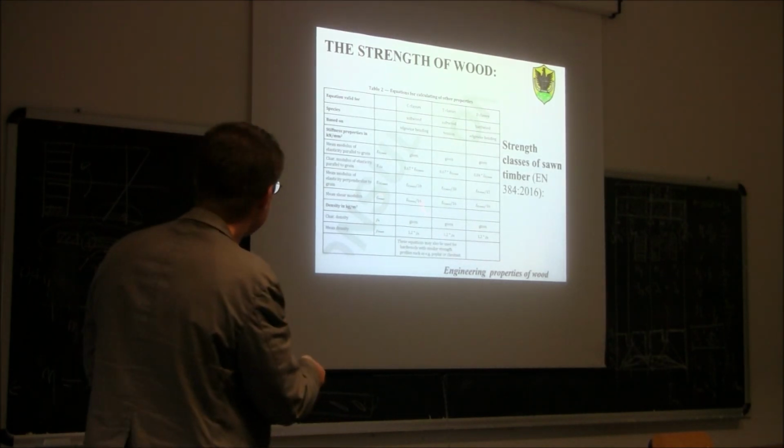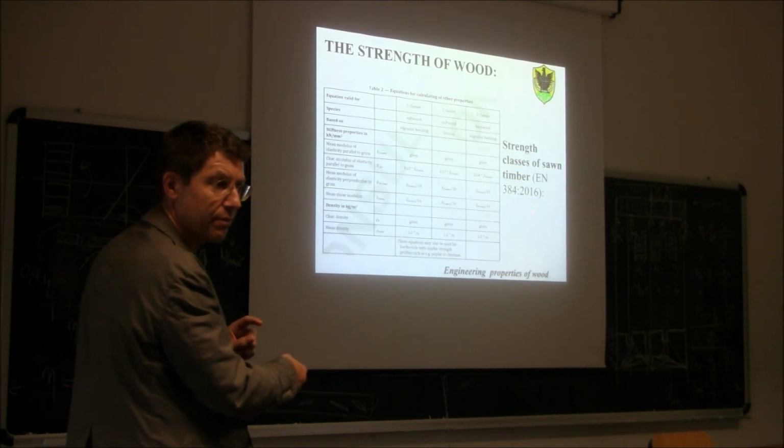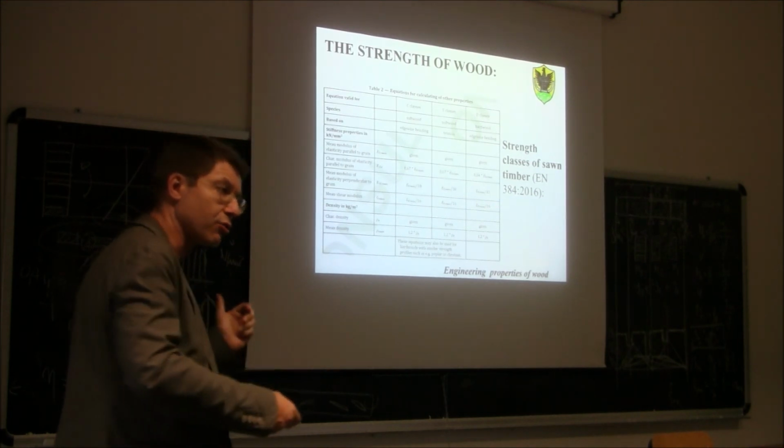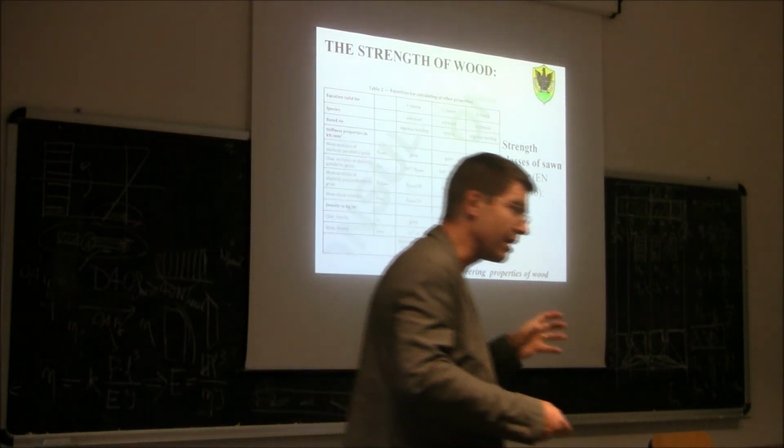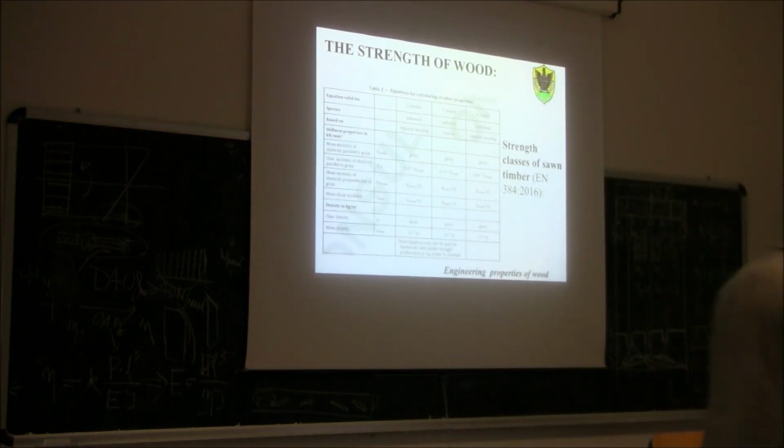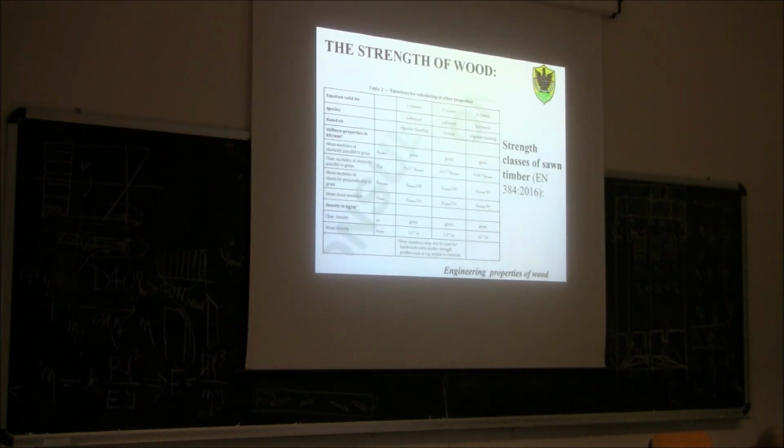Let's see here, 1/16. So for an anisotropic material like this, G is not 1/3 of E, it's 1/16 of E. So it's much lower. It's basically 16 divided by 3, about 5 times lower.